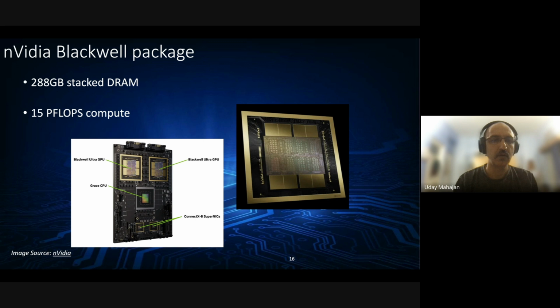You would have 200, 300, close to 300 GB of DRAM on a single package. And if you look online, there is a rumor that the next generation will, in fact, increase the DRAM usage to 1000 GB, to a terabyte. So the scale is just mind-boggling, right? And none of this could have been possible without through silicon vias.